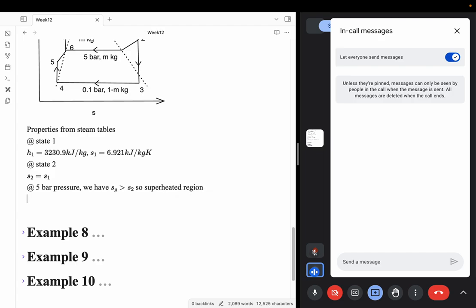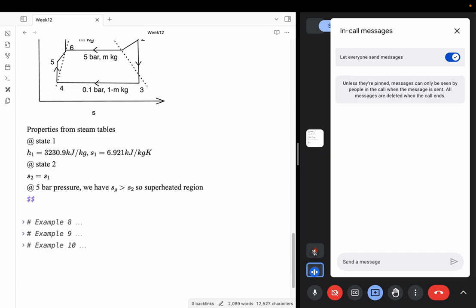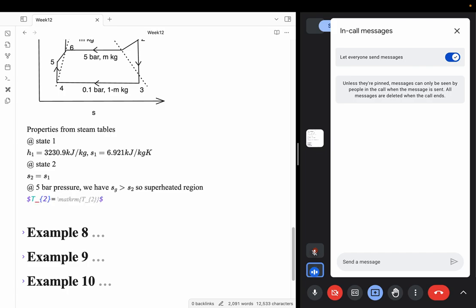Once we know we are in the superheated region, all we need to do is take the table properties at the superheated region. So what is the temperature and pressure? The temperature comes out to be around 172 Celsius, and at that particular temperature H2 is...